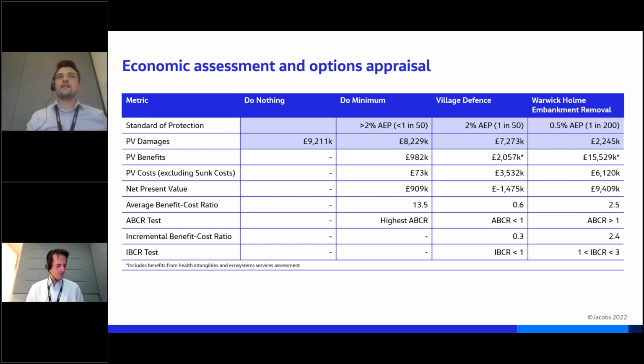So every time a flood occurs and floods somebody's house, there is a monetary damage associated with that flood happening. New carpets, having to dry the property out, new electrics, whatever it is. There are all sorts of different elements of flood damage that can be quantified from a monetary perspective. And Flood Modeler gives us the outputs in terms of flood depths, flood velocity, hazard metrics, etc., that are used to then feed into the economic equations that then return for us these total present value damages that we then use in our economic assessment.